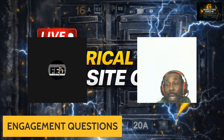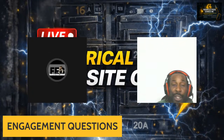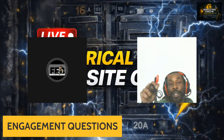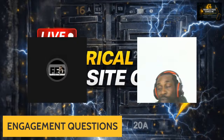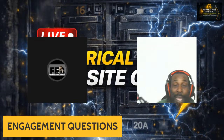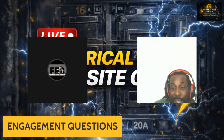After I removed the device from the wires, turned the circuit off, put my leads on, and turned the circuit back on, it lit up red, orange on the screen. That's an open ground. The beauty of the tester is that it's digital, and it tells you everything on it. So that is the third video.